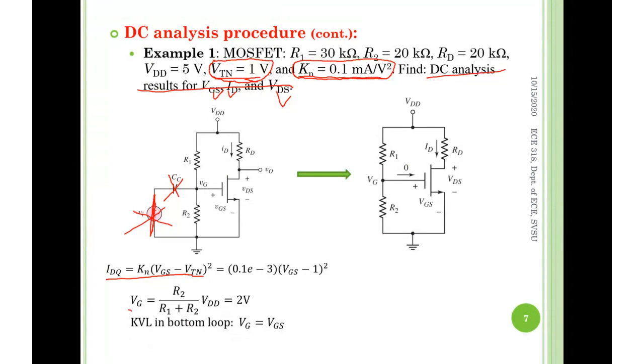Second, this equation is what? It's a voltage divider. Voltage divider means your R1, R2 are sharing VDD. Okay? It's connected. Because here is open. Remember, we just mentioned this is the open circuit. Here is nothing. So R1, R2, they're series connected and they share the total VDD voltage from the top to bottom. Does it make sense?